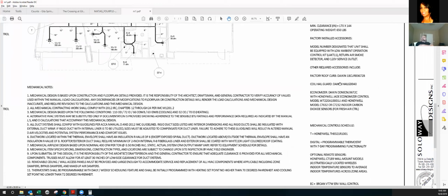In fact, probably the easier way for me to say it is I would expect an experienced TSM to be able to quote the equipment, to go through the selection like we did and say, okay, I've sized this right. I've picked the heat pump. I've picked the gas pack, to select the equipment, select the proper curb, or use CDI curbs to select the proper curb adapter. And then also to be able to quote either the manual damper or the economizer. Those are very common in commercial. In fact, fresh air is required in all commercial applications, a fresh air intake.